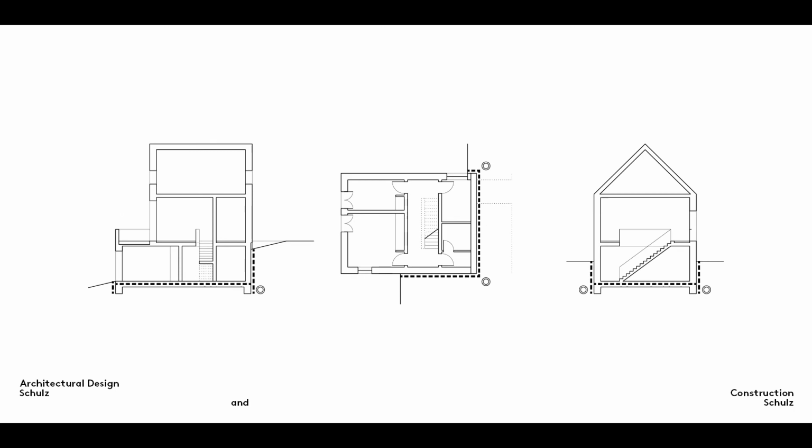In addition to transferring building loads from the superstructure to the ground, foundations play 2 other important roles. Firstly, a building must be protected from external damp caused by groundwater, rainwater and vadose water running down slopes, downward percolating rainwater, and ground moisture. The underside of the house and any components located in the ground must be sealed from the outside.